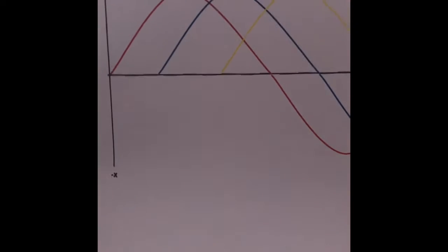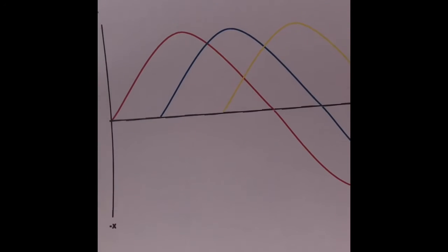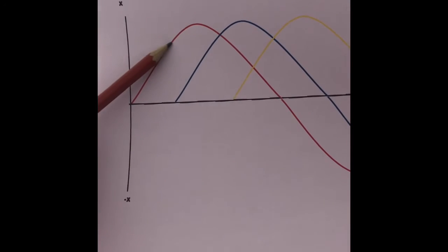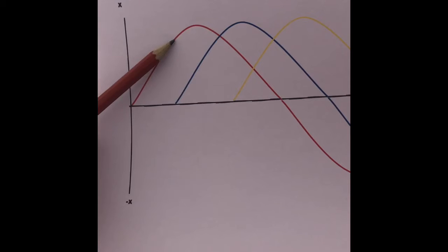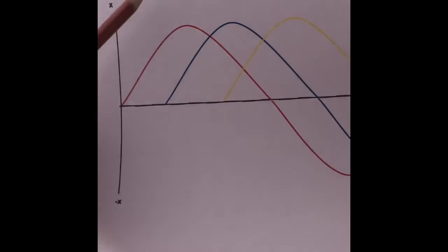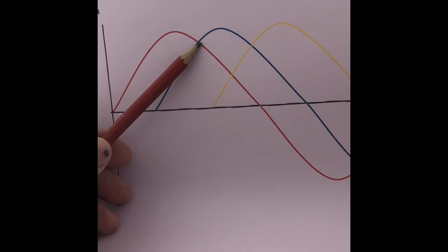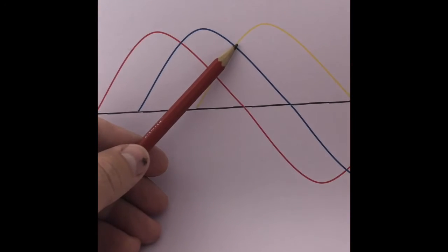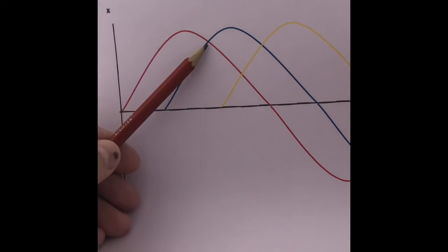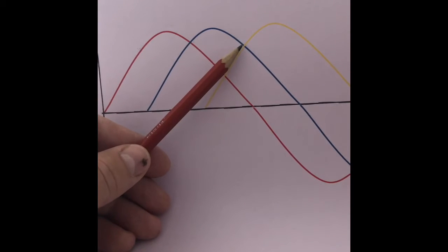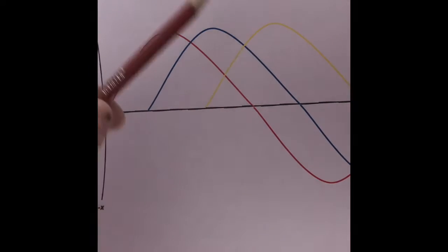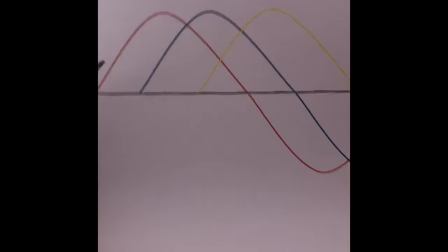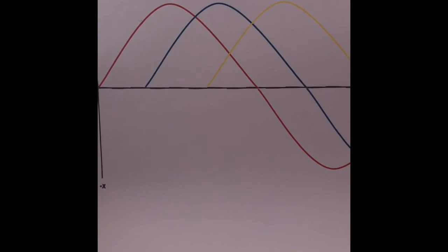What I'm going to show you from here, though, is if we were to take our starting point, so our RMS from each of these. So RMS starts on this point here on our single phase, on our first phase, sorry. Our RMS is then achieved on our second phase at this point, and then our RMS on our third cycle is achieved at this point. These are all measured at 120 degree cycles, so they are basically split into the 3 sets of coils, separated evenly apart, each at 120 degrees to each other.